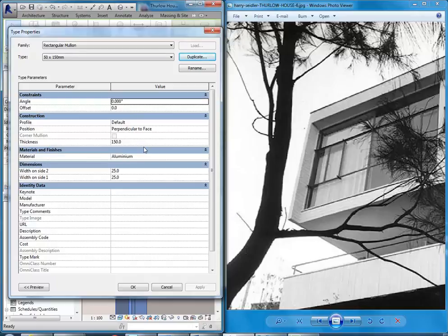So just click into empty space, and then just do a new window. Just make sure it's a bit closer. So just do it from there. Just click and drag. Yep, that's it. Let go there. Go to Filter now, and then see how many mullions come up. So just go to Check None, and then tick mullions. Yep, and then click OK.